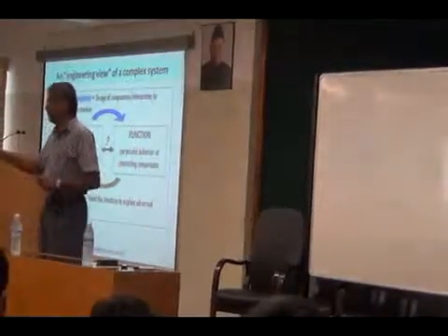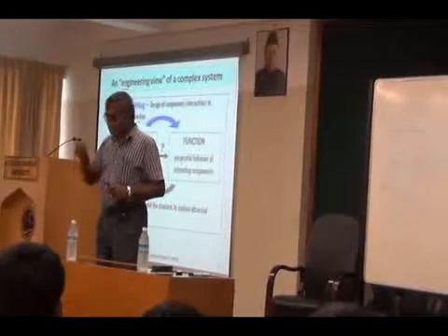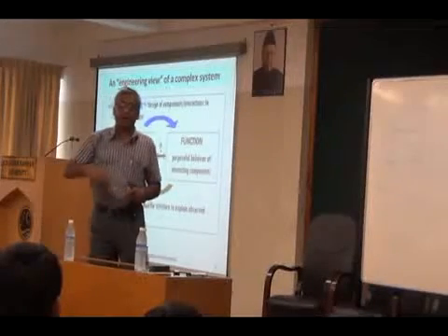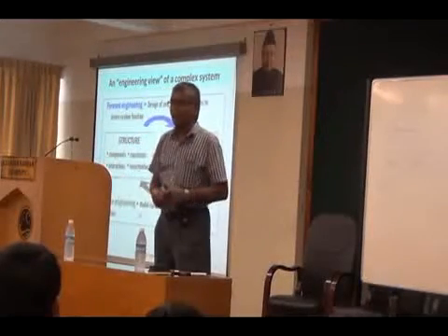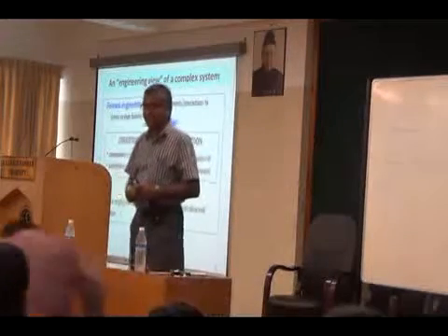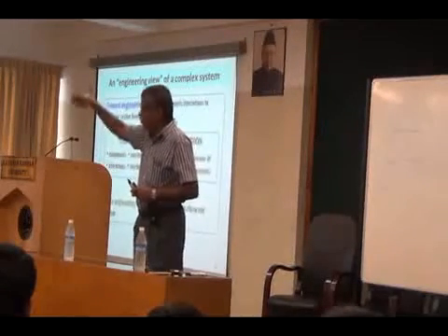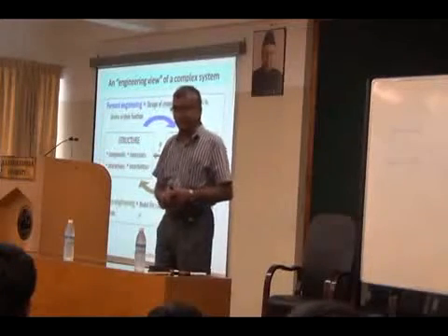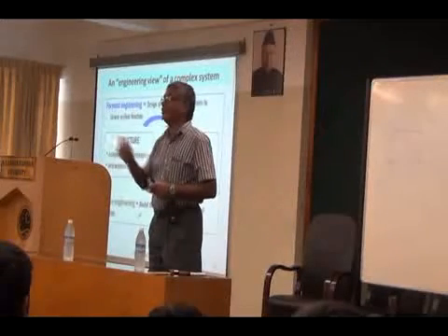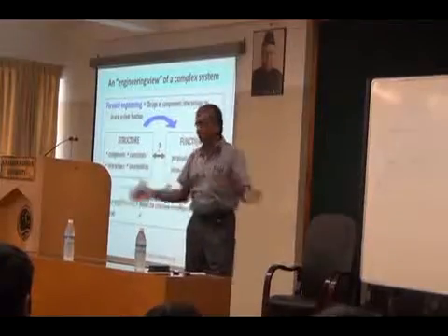When I am switching on the light, I want to see the room illuminated. If it's not happening, I know there is a problem with the bulb, or the circuit is not closed, or there is no power. If the bulb is okay and there is power supply, still I switch on but there is no illumination in the room, then obviously the circuit is not closed. That means the switch is not doing its function. That is a failure. Now look at how many keywords have come.